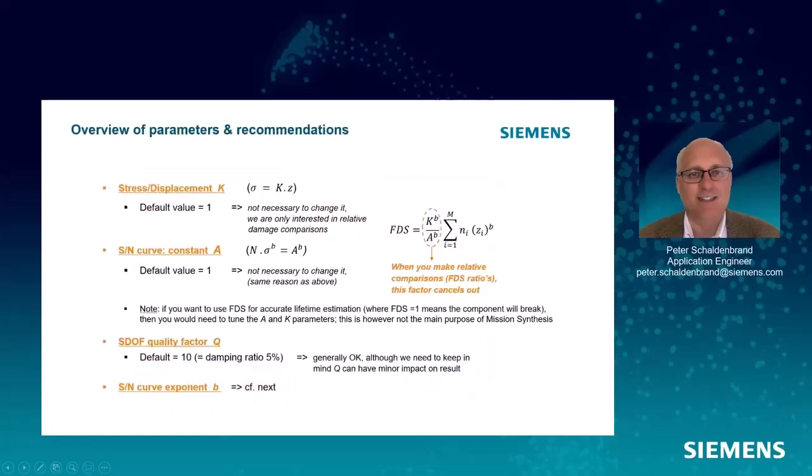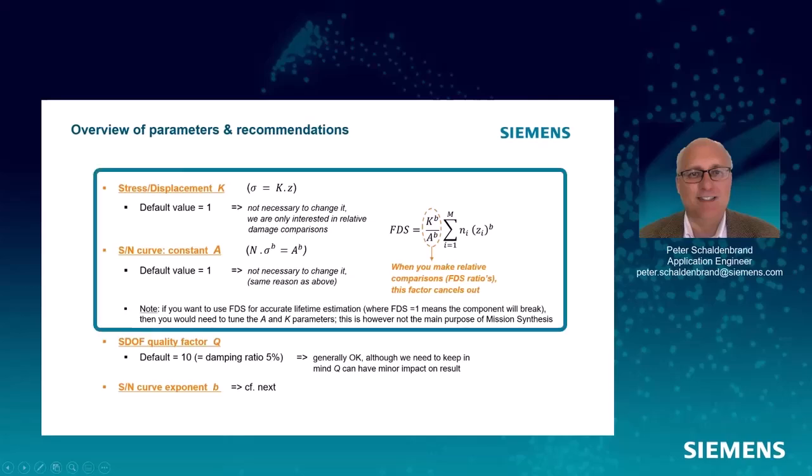In the software, this is a little bit confusing. You'll see a K and an A. I've really never seen it used, but it's there to calibrate this acceleration to a relative stress. It's not really needed in the process because we're doing a relative damage comparison. But if you wanted a more precise damage comparison at one spectral line or one filter frequency, you could use this.